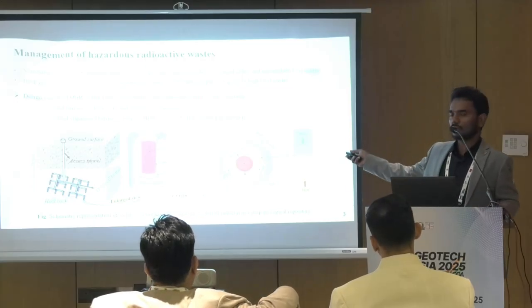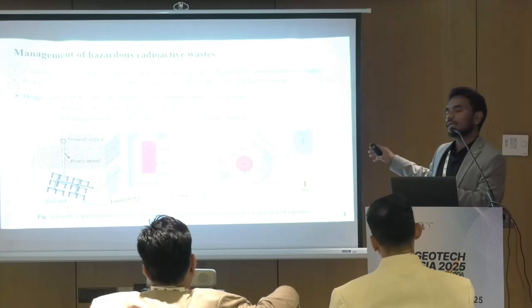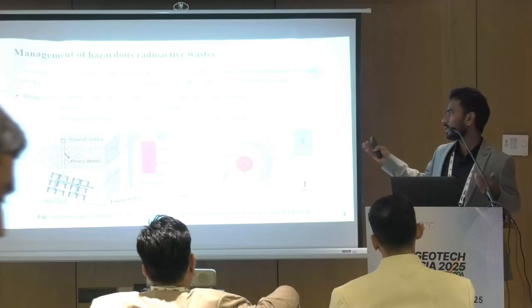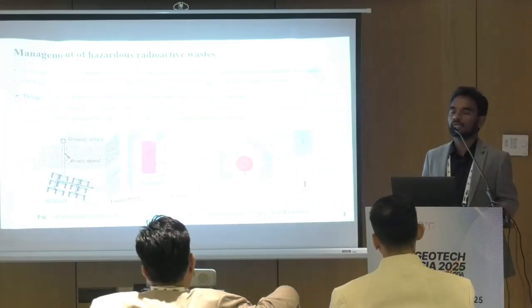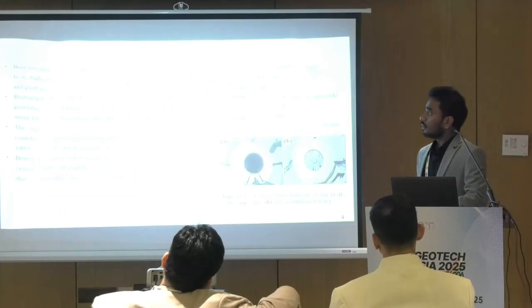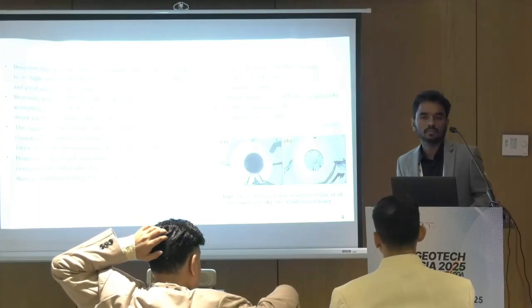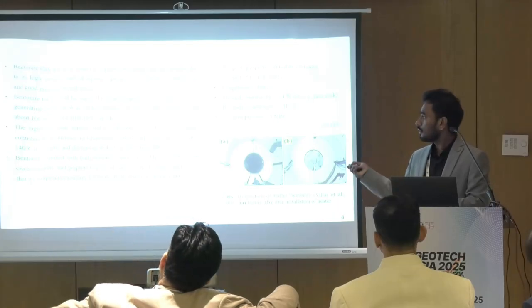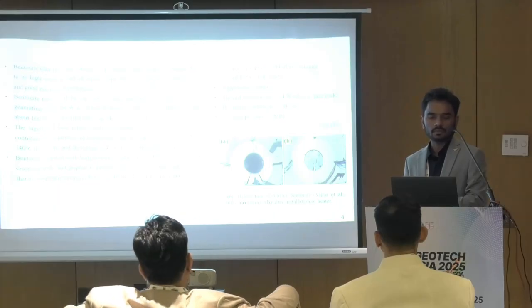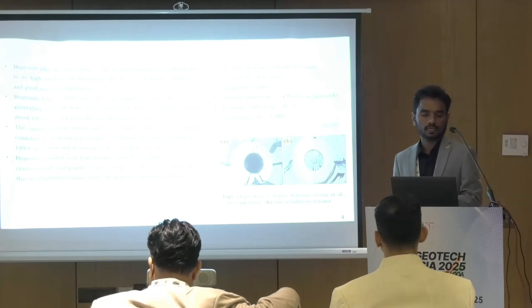If you see the cross-sectional view, from one end the heat is generating and from the other end the water is coming. Under this coupled condition of heat and water, the topic is thermo-hydro-mechanical behavior, or THM behavior of bentonite. Bentonite clay has been valued as a promising buffer candidate due to its high swelling nature, low hydraulic conductivity, and good mechanical performance.